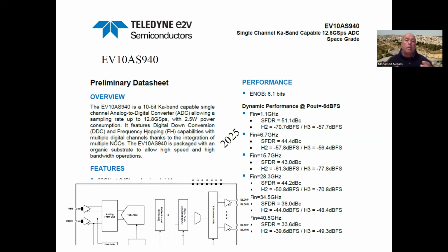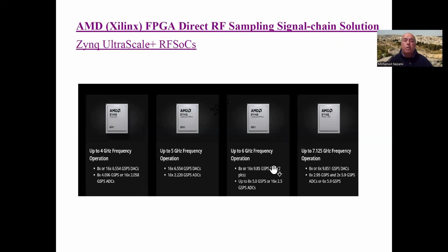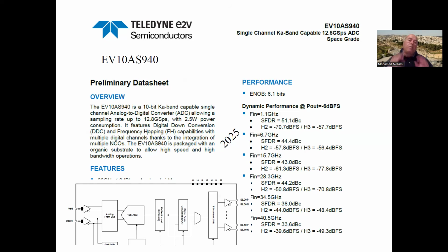Remember, in direct RF sampled receivers we don't have a mixer, so there is no frequency planning in terms of LO, spurious, and harmonics versus the RF carrier signal. But we do have to worry about the ADC now having an interleaver, because there are multiple converters and mismatches between them. You get spurious from the interleavers, spurious from the mismatches between the ADCs, and you've got harmonics of the RF itself.